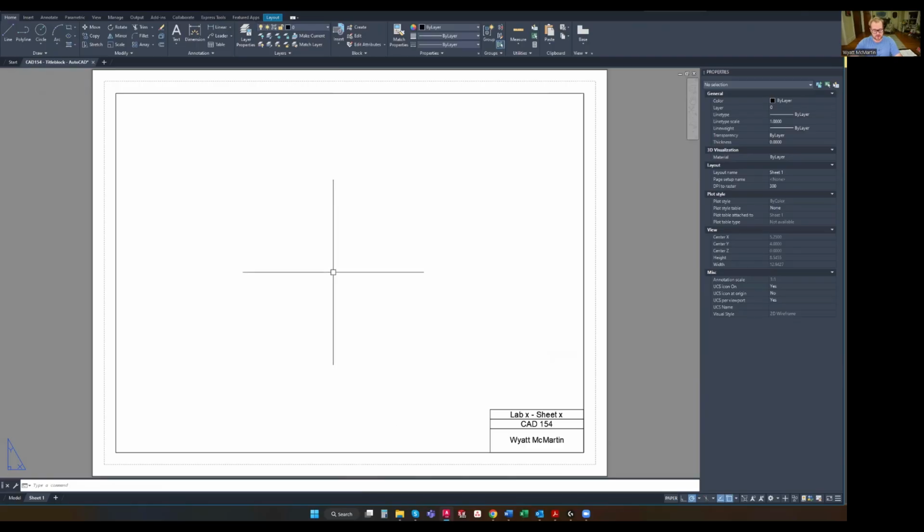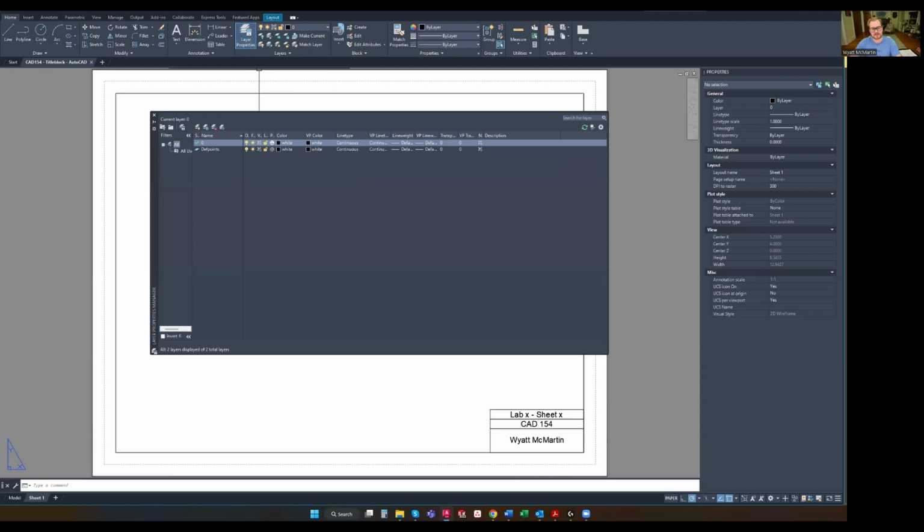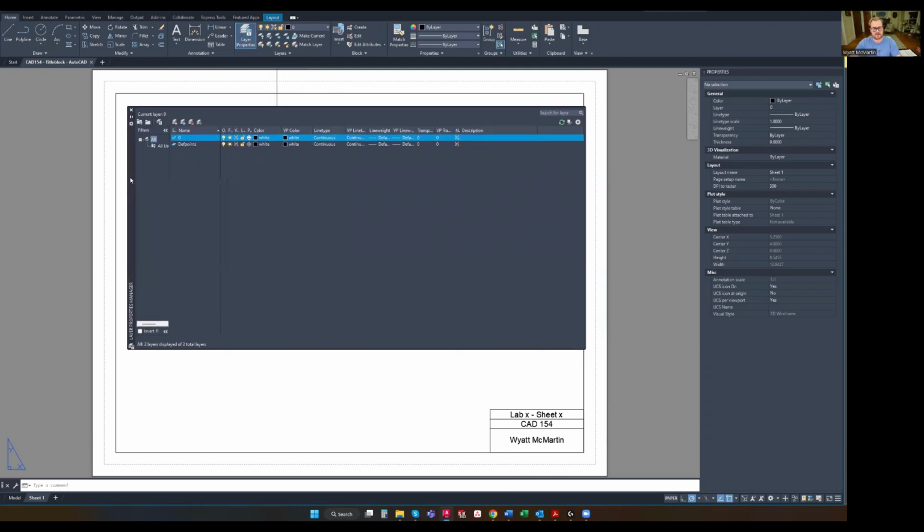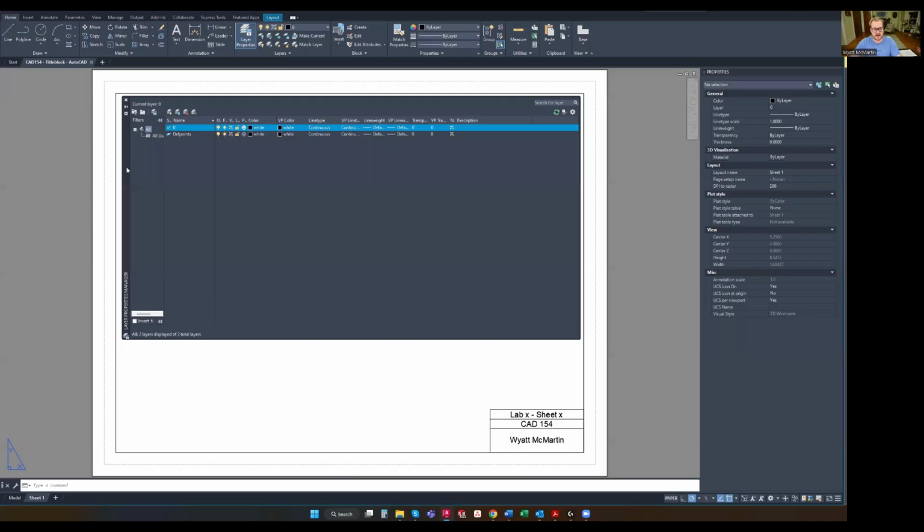Once again, Control S. And the last thing we're going to do, I know I talked about it briefly, I think it was last week. I'm going to click layer properties. And we are going to add a few layers because for this week and next week, which are the last 2 weeks of AutoCAD, we're going to be utilizing a tool within AutoCAD called layers, which is very important in terms of organizing your drawing so that you can easily manipulate specific areas of the drawing later.